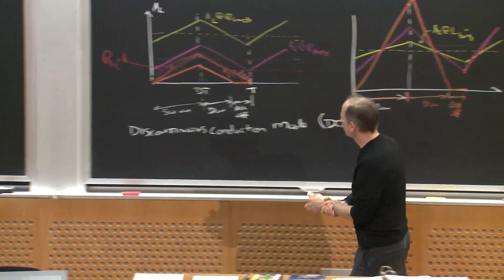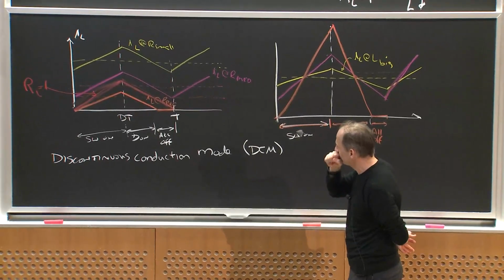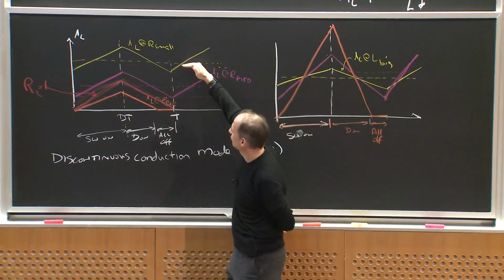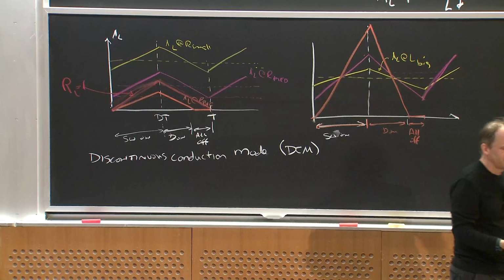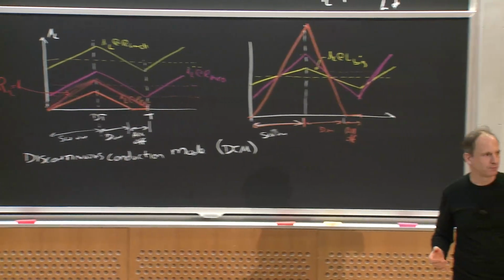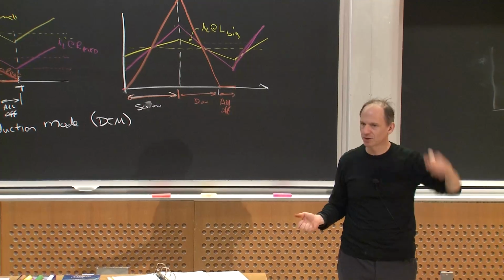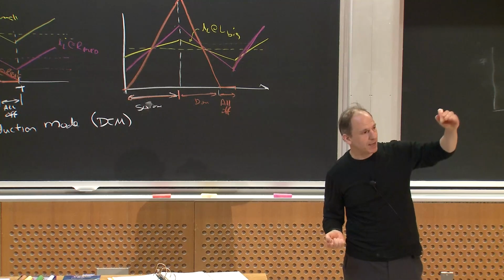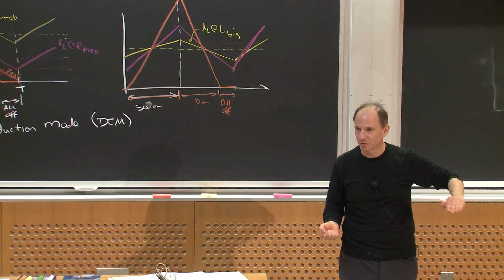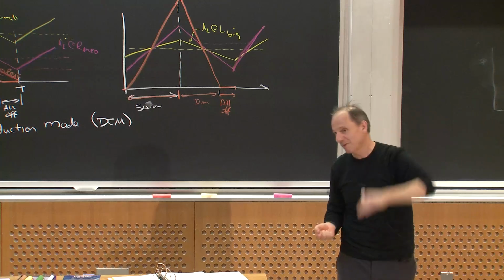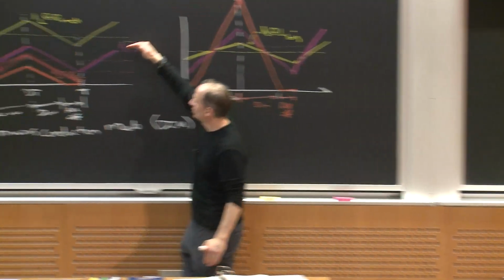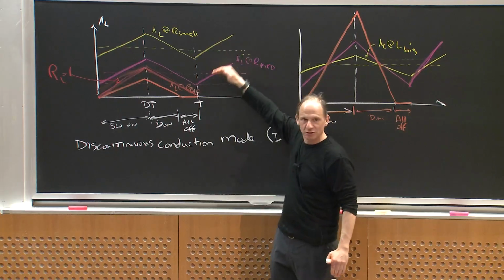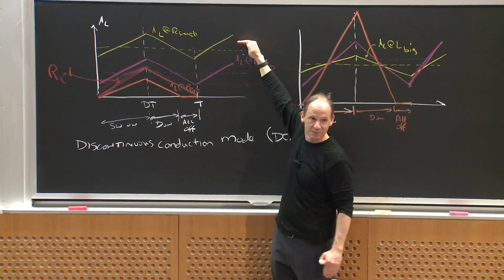Why? Because think about it this way. I have to run for different load resistances. Mostly in a power converter, you build the converter and then people hook loads up to it. You don't know what load they hook up to it. There's some maximum power rating, but maybe they want to put very little load on it sometimes. Maybe sometimes your microprocessor is running, maybe sometimes it's not. And so you might have to deal with a very wide range of load currents, up to some maximum.